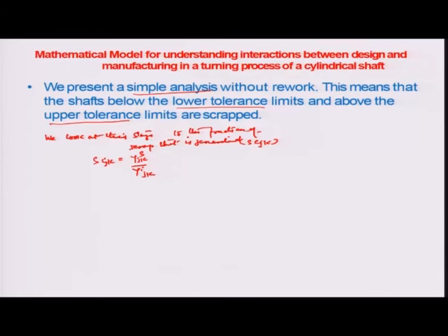transformation process as scrap. So, if I look again at the normal distribution and the way that rejects are determined, you know that there is a process mean, and obviously there is an upper tolerance and a lower tolerance, corresponding to which there is a z variate which has been plotted. So, there is a z variate lower and a z variate upper. This corresponds to, let us say, the upper specification limit of the kth specification system and the lower specification limit of the kth specification system.